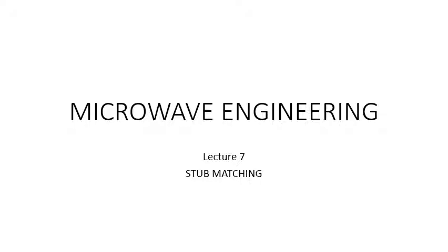This is another form of impedance matching technique in which we are going to use distributed matching, meaning your final design will not be in the form of lumped elements, inductor and capacitor, but will be in the form of microstrip lines. They can be connected either in series or in parallel. This is stub matching, and in this stub matching we are going to use only short circuit or open circuit stubs, which will be shown in the consequent designs which we are going to see.